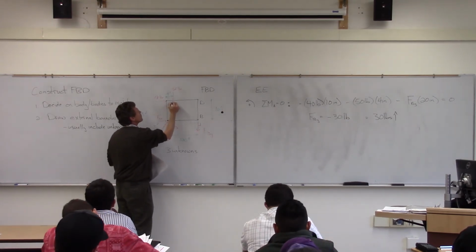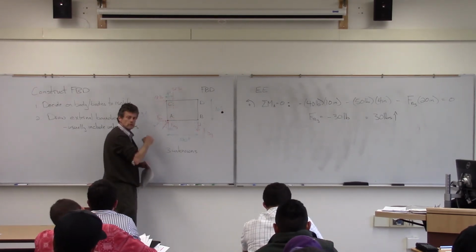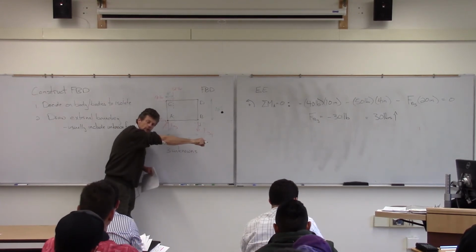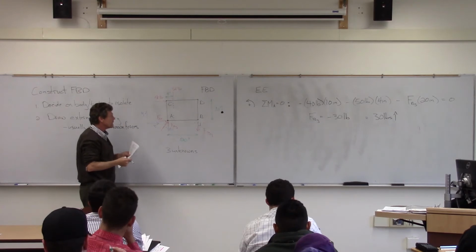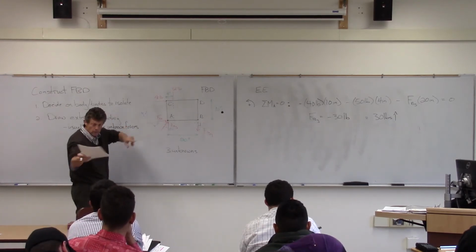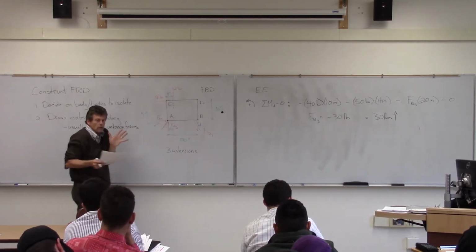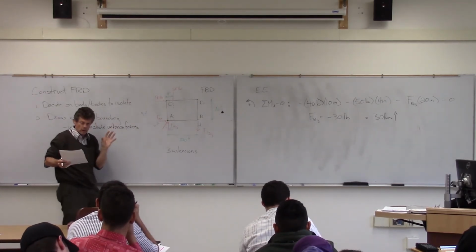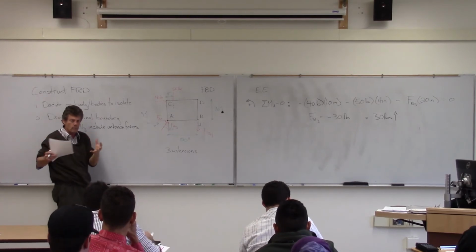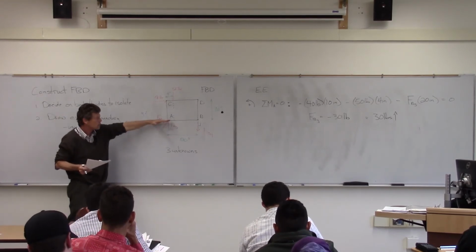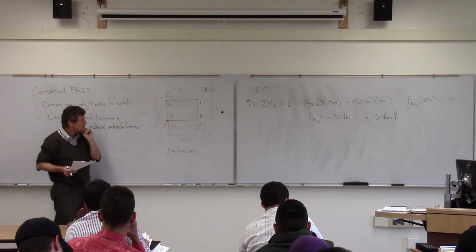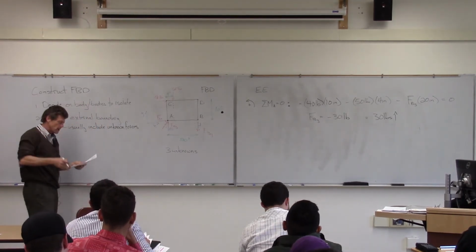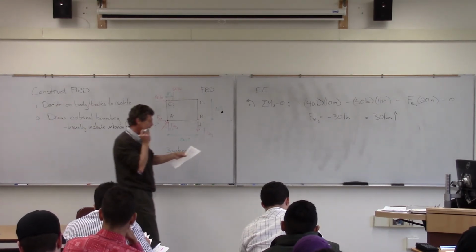Because it's going to be the perpendicular distance to that force. My force is acting vertically down, so my perpendicular distance is going to be in a horizontal direction there. If I do my cross product, I can do that; anywhere along the line of action is fine. But again, I'm looking at this in terms of a scalar approach, and my definition of a moment is always going to be the magnitude times that perpendicular distance. It's a good way to think, because even when you do cross products, it's easy to screw up, and you can sit back and think about that.